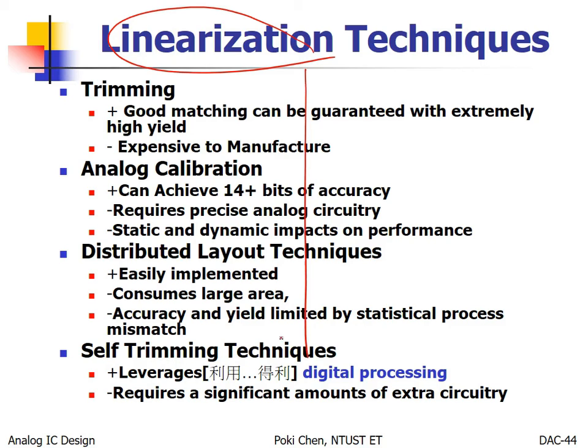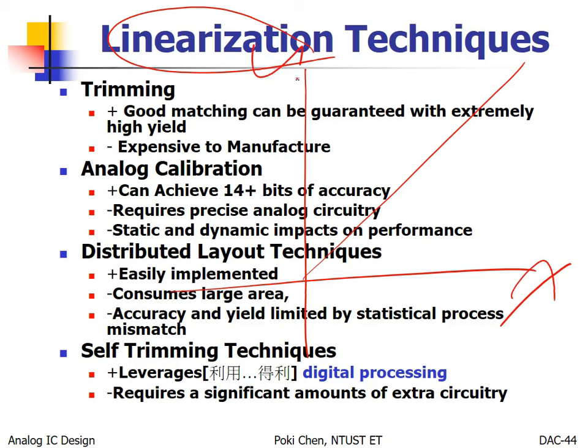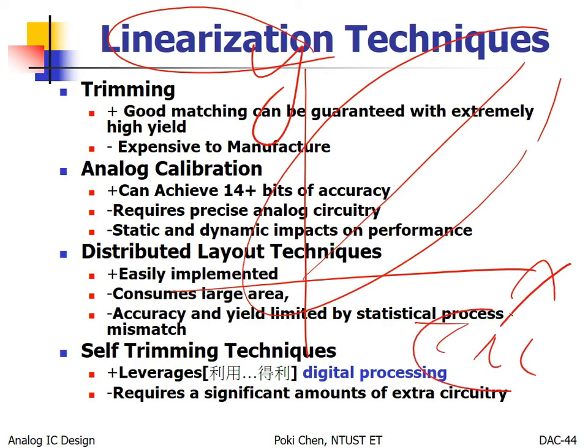Simply, as I told you from the beginning, never mind what kind of conversion, we hope the output looks like this, right? That is your input, and this is the output. We hope the dependence looks like this. It is a straight line. That is what we want. And how to measure the linearity? For data converters, we have INL, right? So if your output versus your input is perfectly linear, then this one should be 0 in theory, right?